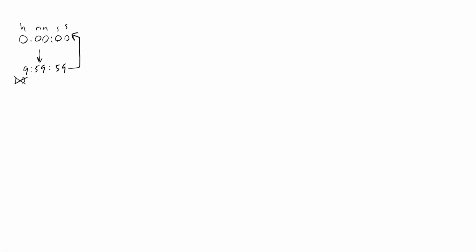So the timers on a microcontroller work much the same way, except they're not counting hours, minutes, and seconds separately. They're just counting in binary. So I have a separate video explaining how binary numbers work that I recommend you go watch first if you're not sure, because I'm not going to go over it here. But the ATmega328P has 3 timers available. 2 of them are 8-bit, and 1 of them is 16-bit. We're going to focus on the 8-bit timer as an example here.